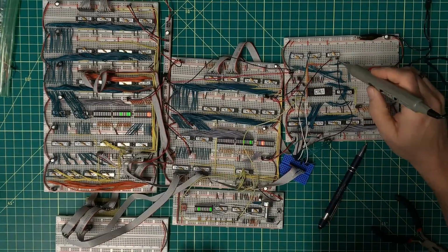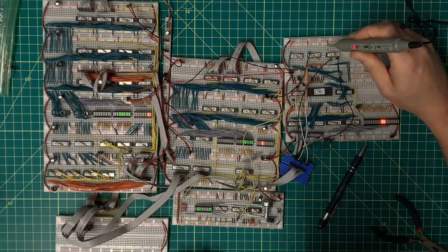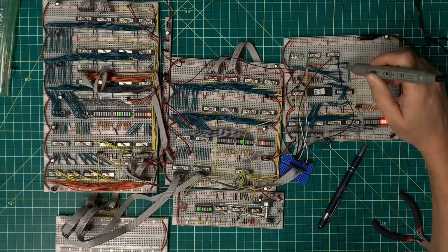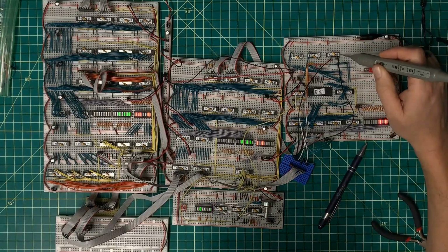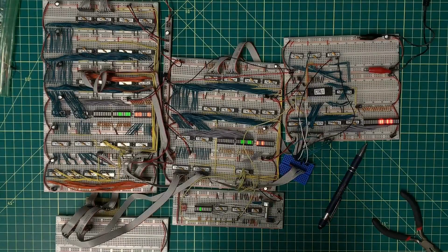So this is now connected to ground, which it should be. This is now 5 volts, which is as it should be. I just had this ground line here in the wrong spot, causing this to produce floating output, which now should completely stabilize this.